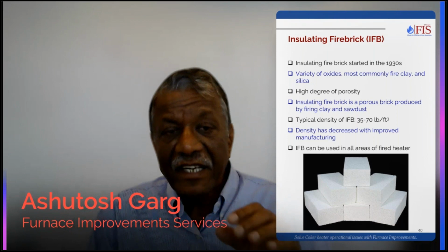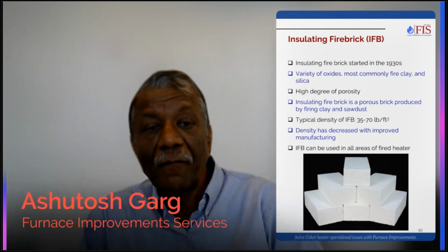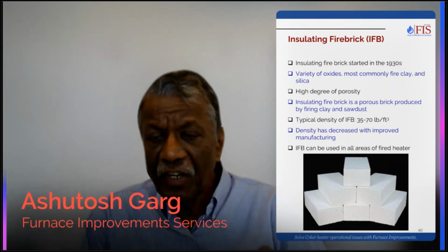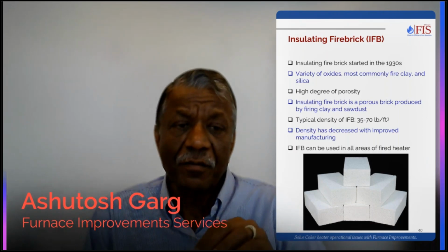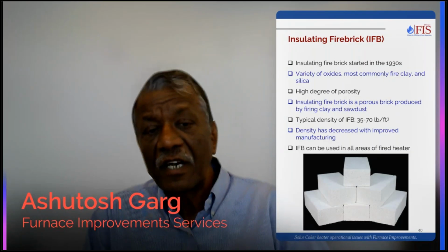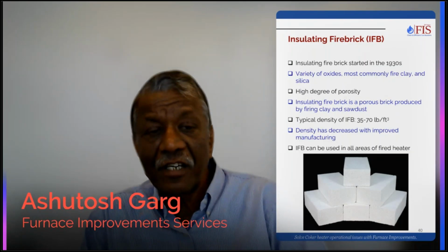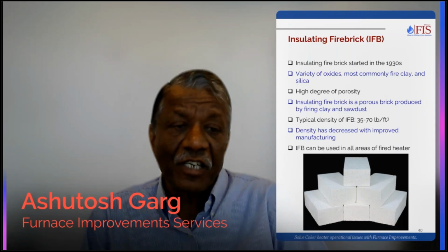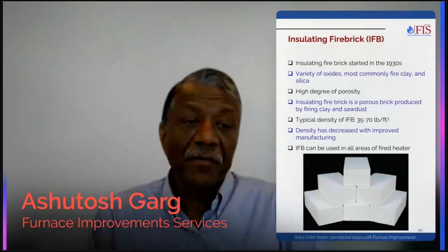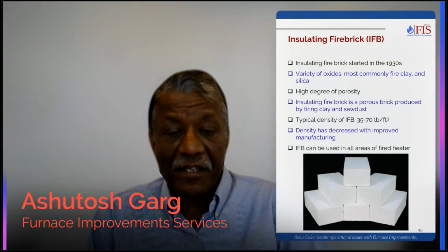But other than that, it's a very good material, high degree of porosity. We can control the quality of the castable, quality of the brick a lot more efficiently. And you can get insulating Firebrick in the densities ranging from 35 to 70, you know. And this can be used in all areas of fire heaters. But as I said, the only downside is the labor.